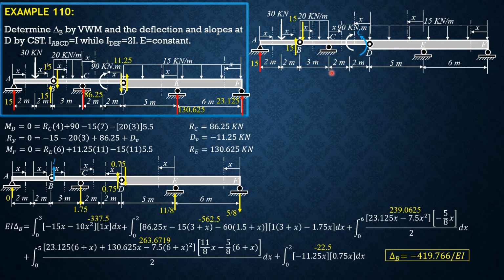So if we sum up moment about C, reaction, assuming upward, times 4, just concentrate on the contribution of the couple because the reaction due to real loads have been determined already in this procedure. So reaction at C times 4 equals couple. Therefore, reaction here is 86.25 plus couple over 4, or plus 0.25 of couple.